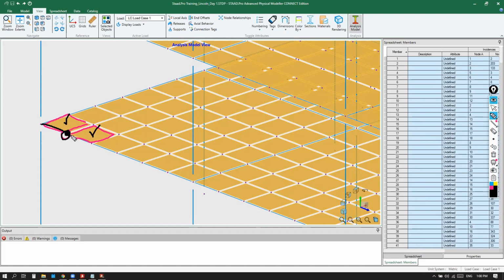For example, if I have the shear force here, I have to have the shear force also here. If I have the moment here, I also have to have the moment here. And the same in this direction for the slab. If I have the moment for a slab in this direction, I have to have the corresponding moment, which means everything should be in equilibrium.